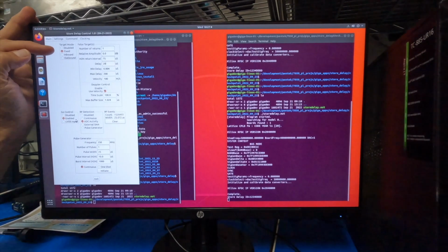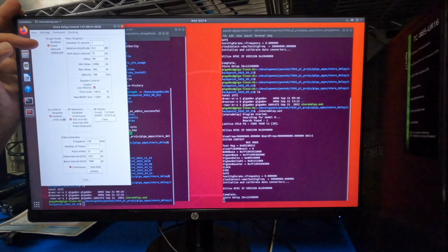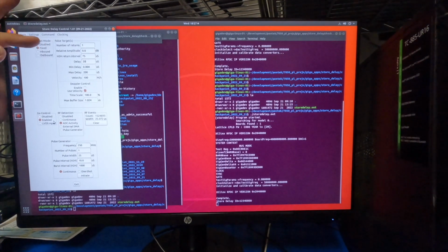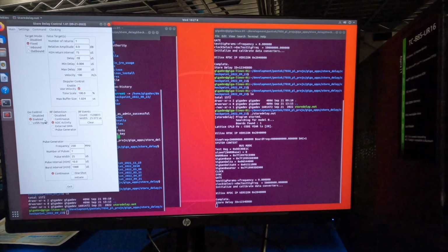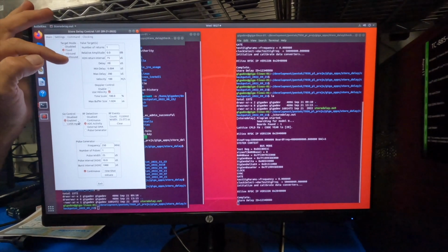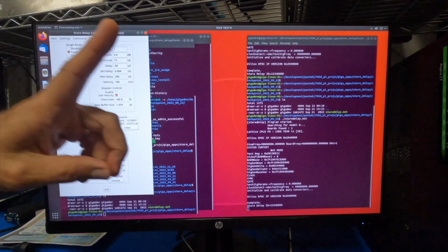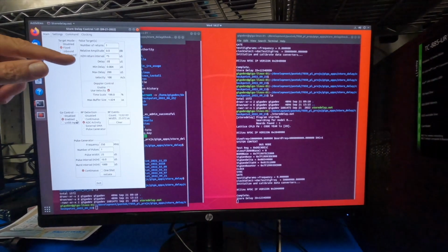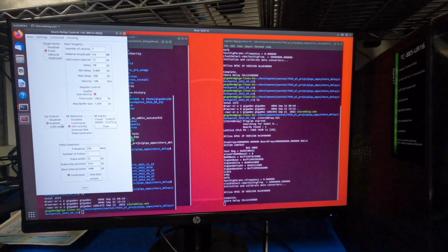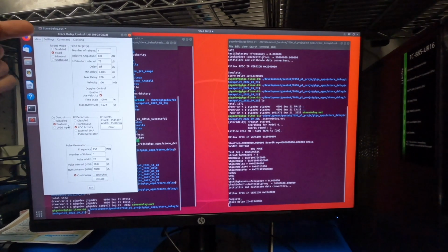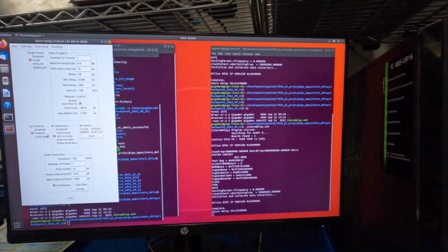So it's either ground to ground or air to air, but traveling at the same speed. And relative amplitude is no gain, no loss. And for right now, head to head doesn't matter because we're only putting out one pulse. But we're going to put out a fixed delay of 20 microseconds after the energy is actually sampled at the beginning of the pulse. And we'll show you that if we go to the digital oscilloscope.